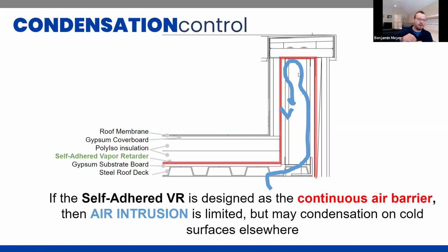If that's a tall parapet or if it's a very cold environment, the top of this parapet can be pretty cold. So we have the ability for moisture from the interior to stay on the inside, but hit that cold surface and then stain the inside of the wall. And you see that many times below parapets, where it's a little bit of a rain factory in some climates if you have a very high moisture load on the inside and a cold parapet up above.